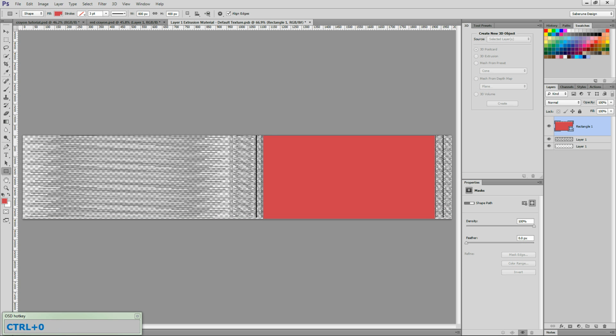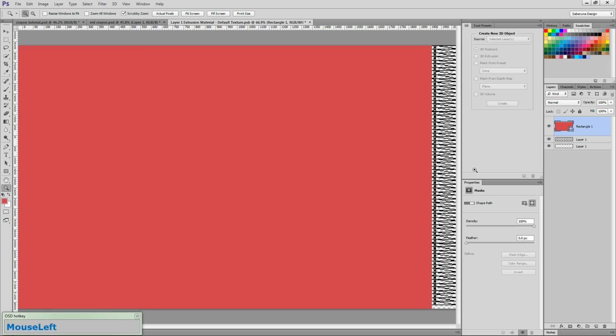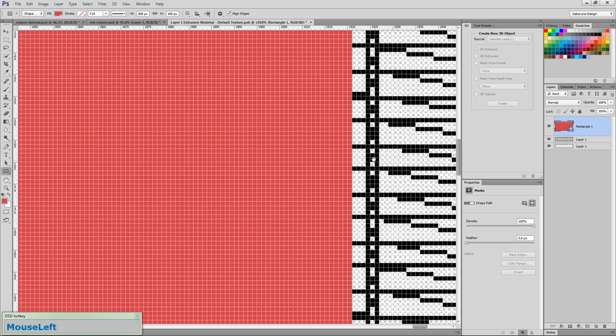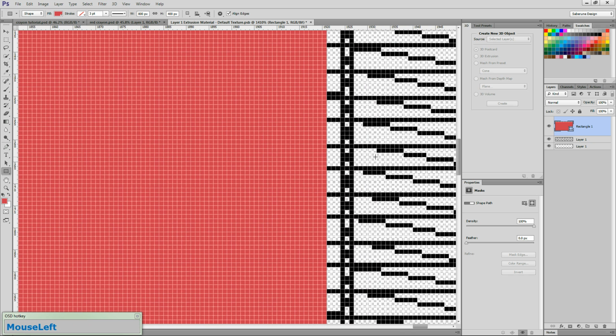Next, let's zoom in close to the right-hand side of our rectangle so that you can clearly see this vertical line in the wireframe guide. Now, the right side of the image corresponds to the bottom of our crayon mesh. As I said before, the vertical lines in the wireframe represent changes to the angle in our mesh. If you'll remember back when we first drew out the vector path, we had two angle changes at the bottom.